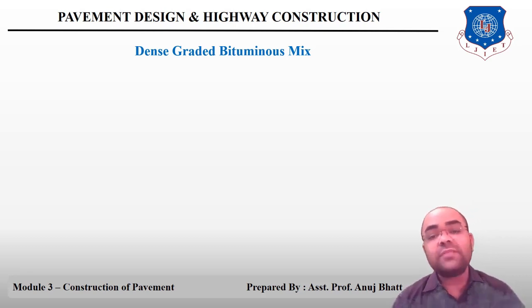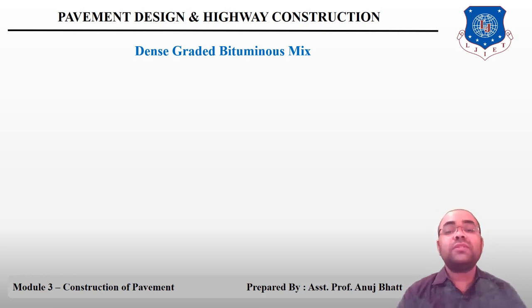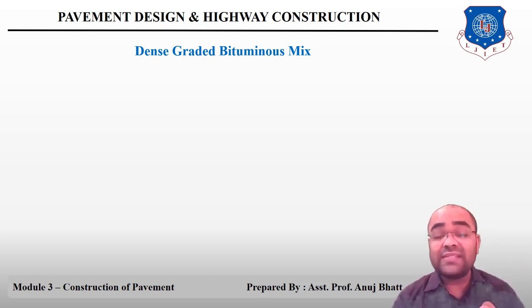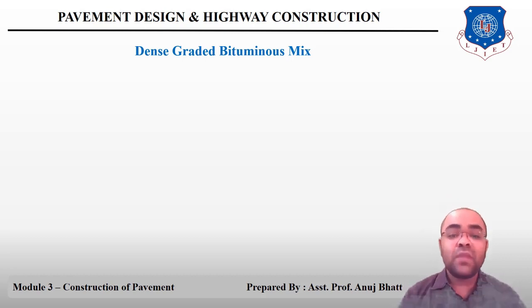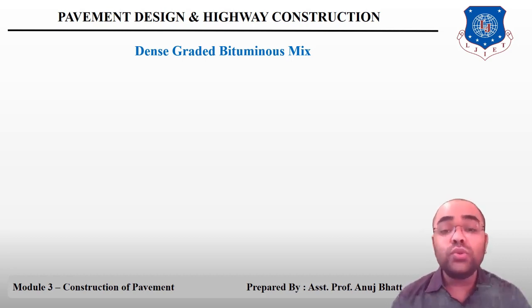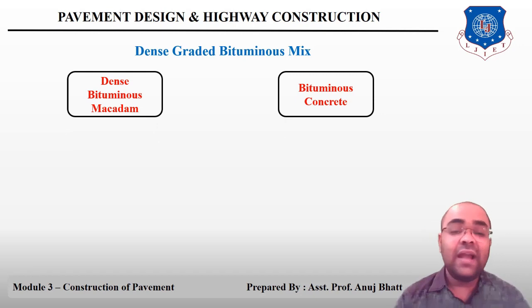Almost all the possible flexible pavements constructed in the world employ the dense graded bituminous mixes. So here you can see the importance of these bituminous mixes. There are mainly two types of dense graded bituminous mix. The first is dense bituminous macadam and the second is bituminous concrete.